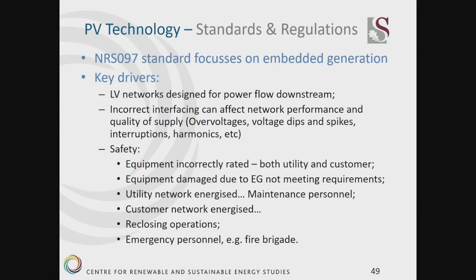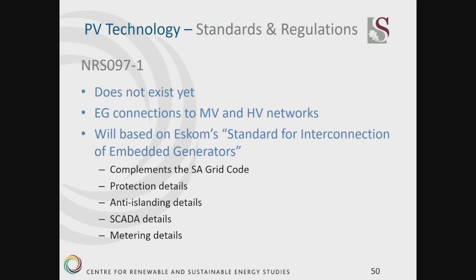This is a safety risk because if the municipality or Eskom switched off the power because they're doing maintenance on the lines and you are feeding energy back into that grid, they don't know about you and the network is actually live, and perhaps something happens and they don't follow the safety protocol or procedure, there might be somebody that gets hurt. So that will be under consideration.